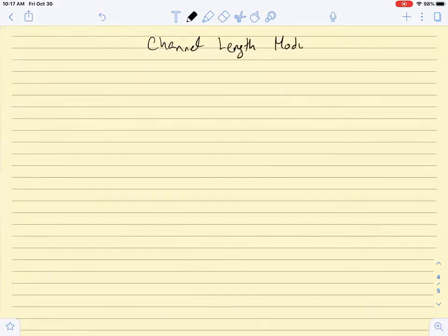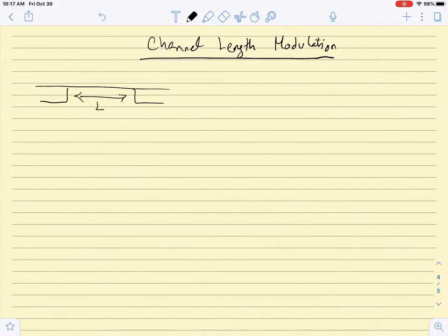What the scientists discovered is that because the channel is not linear, and we will explain this in other courses, what happens is, although I have a certain channel length L, okay, when VDS becomes very large, L is going to drop, and therefore L for the channel is going to change.